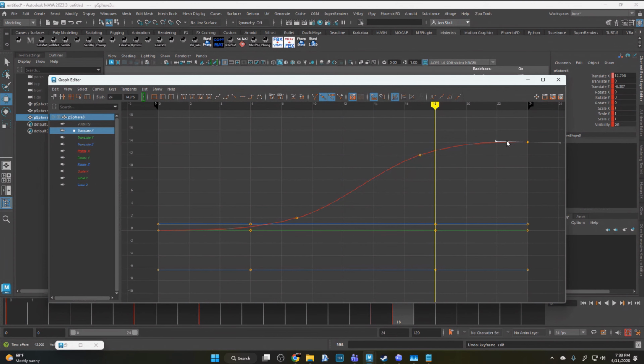Yeah. But I don't like weighted handles, because if I have like 1,000 keyframes here, I'm trying to keep up with which ones are weighted and which ones are not, and I'd rather not do that. I see. I'd rather them all be consistent, and they can only go this far, and then I control it with keyframes.